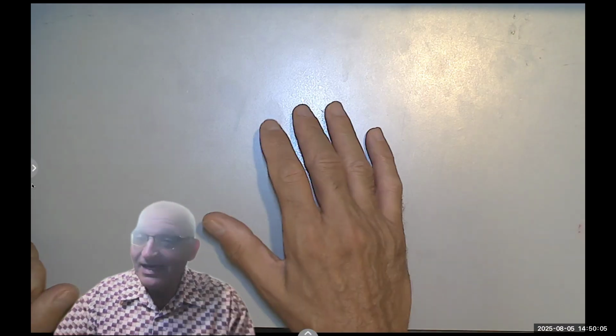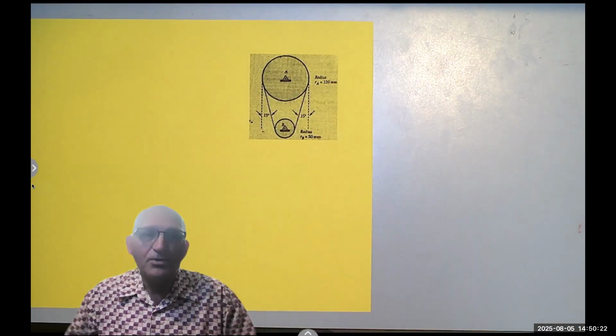Last time, we derived the equation between the two tensions in a drum when it's rotating either clockwise or counterclockwise. I've taught this course for years, and we always assume T2 is larger than T1. But when I copied that from an online site, they had T1 as the bigger. So I hope this doesn't confuse you. Just think which one is the bigger, and it equals the other times e to the mu sub s times theta, or beta, I'm sorry. So that's another problem here.